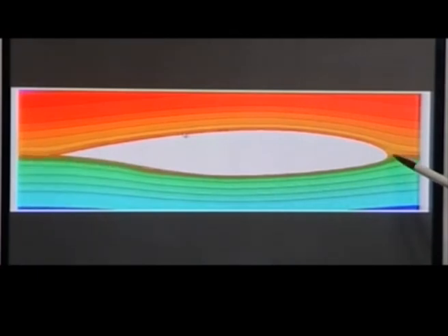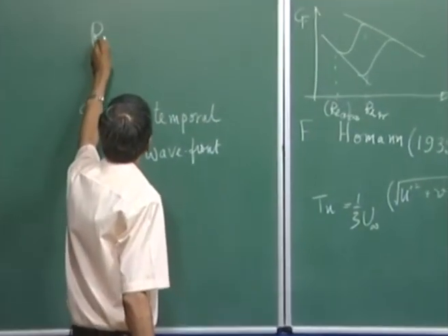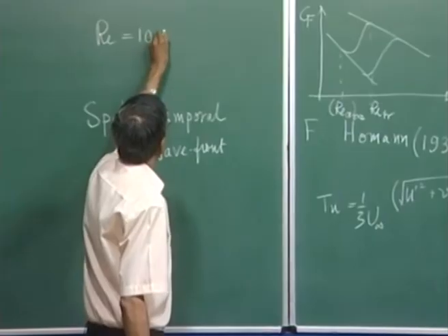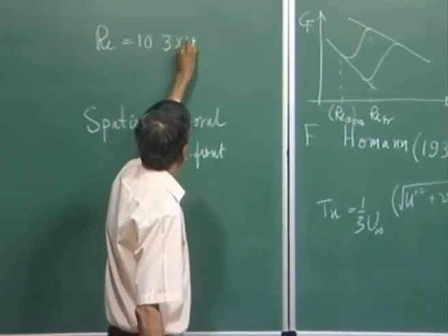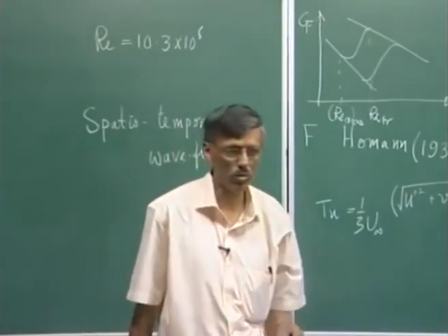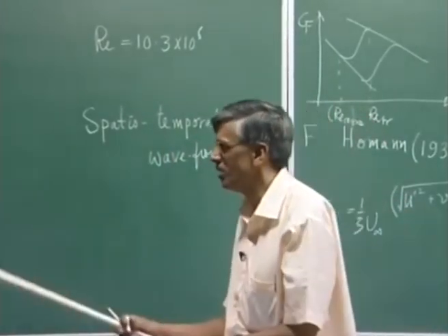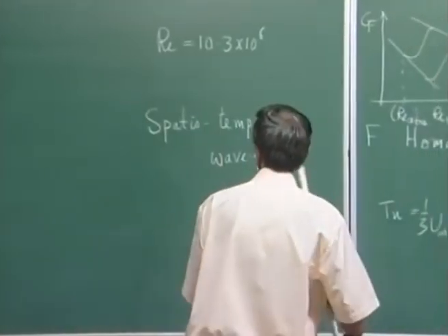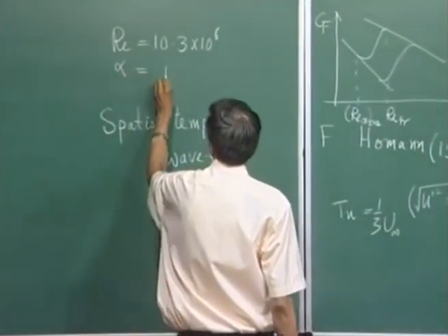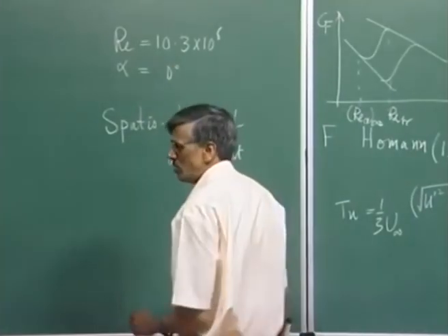Yesterday you recall we saw that Honda aerofoil, and what we see is that if we perform the simulation for this flow going from right to left, this is the simulation for a Reynolds number of 10.3 million. This is the cruise Reynolds number for that Honda jet, and this we can compute without any models, right. We can do it, and this is at a 0 angle of attack. So, the flow comes without any inclination.